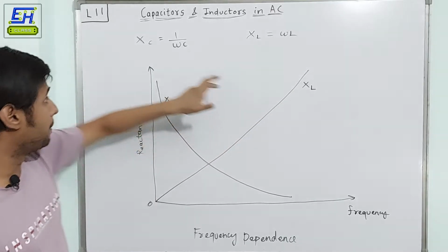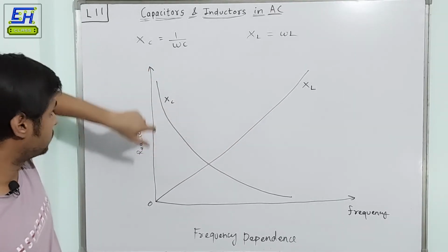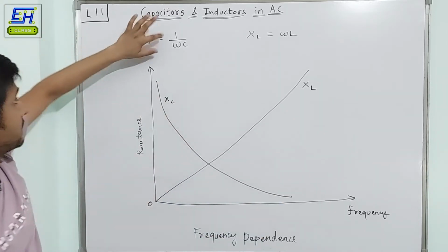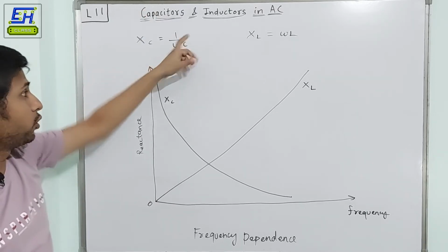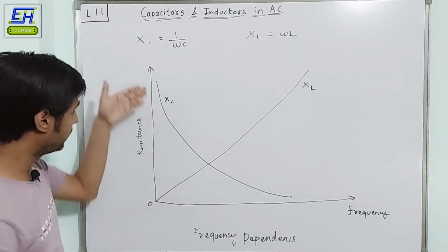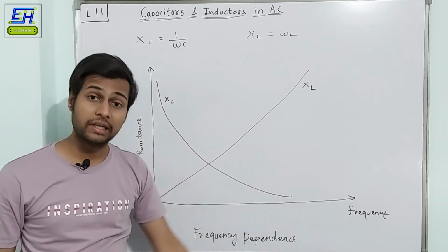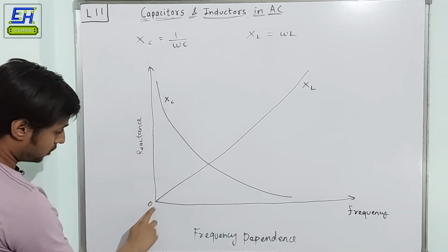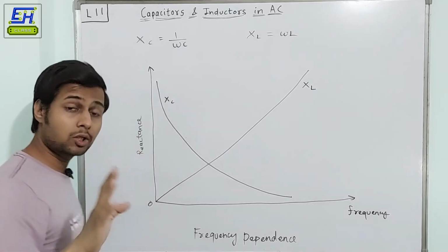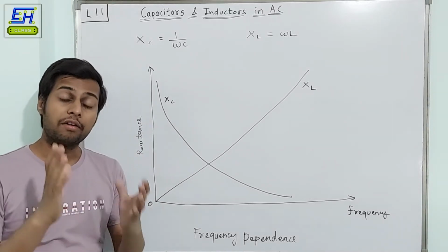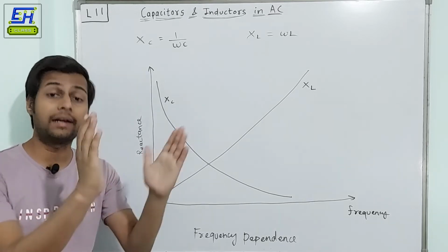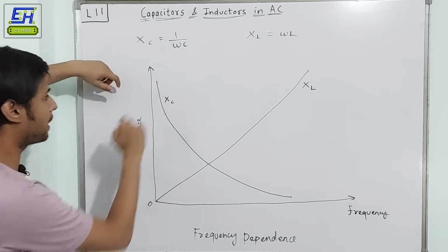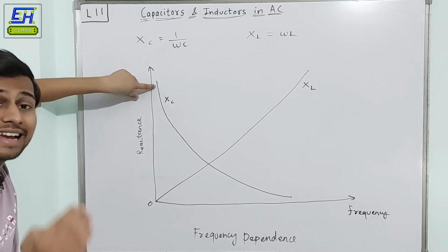Do remember. But in the case of capacitive reactance, it is somewhat like an exponential decay, because it is inverse. Even if you calculate mathematically, this is correct. So from this, what can we conclude? First, for a capacitor, let's see lower frequencies, frequencies closer to zero. Frequencies closer to zero actually mean that we are providing a DC signal, more DC characteristics. So if you provide DC or a very low frequency signal to a capacitor, it will provide a very high reactance, very high opposition.